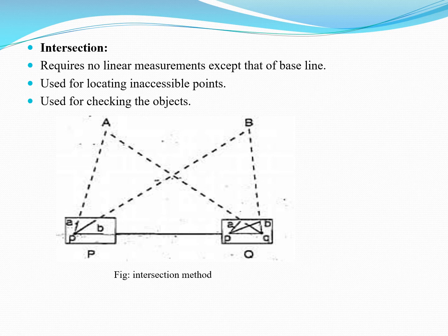Okay, so the plane table is then oriented by any one of the methods of orientation to make the connection of the next station. So before every setup of the plane table, we shift the plane table. There we must do the orientation of the plane table.